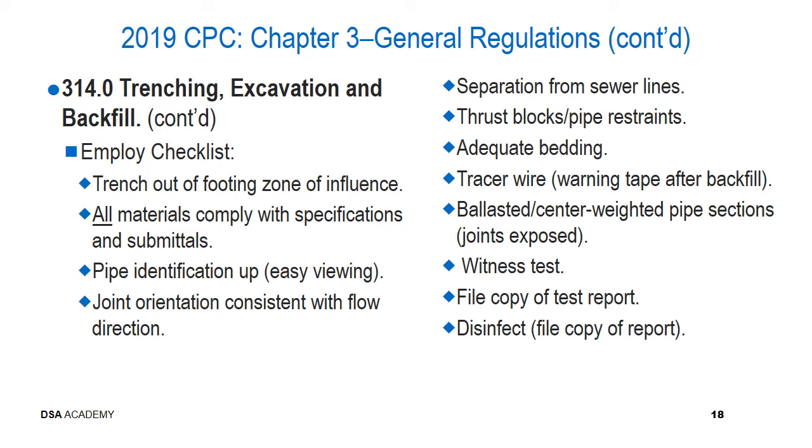Remind them that when they're installing their piping, that the labels are up. As we all know, all piping is labeled longitudinally at 180 degrees out from each other. So it would behoove them and you to make sure that you can inspect and verify that the piping material identification labels are pointing up to ease your inspection.